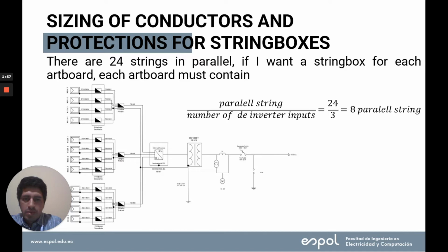The worktable also has 2 vertical and 18 horizontal panels connected, and the secondary string box will have a fuse for each string or parallel panels, and a main circuit breaker for each one. The fuse current is 10 amperes in DC.